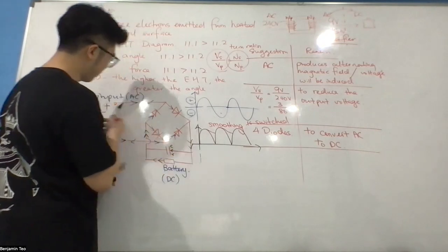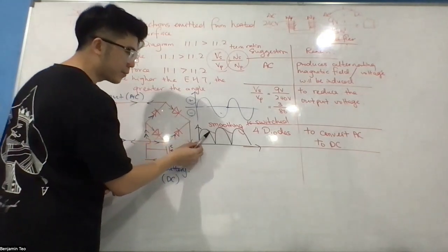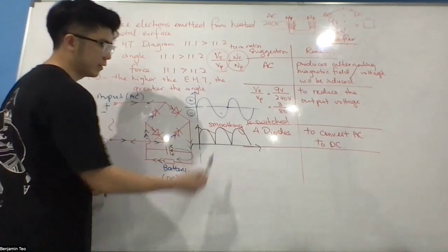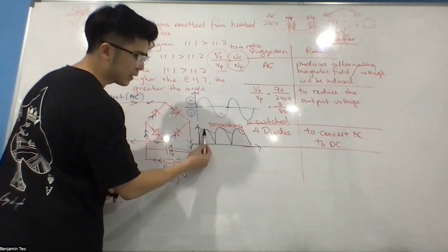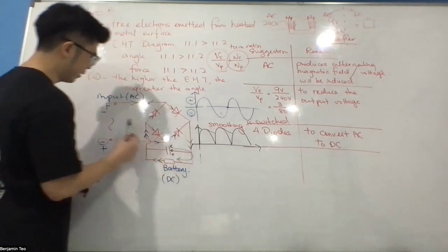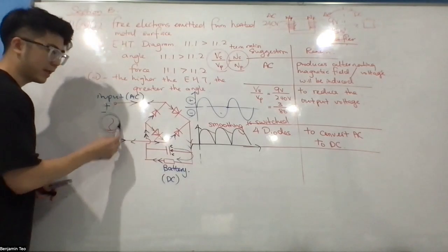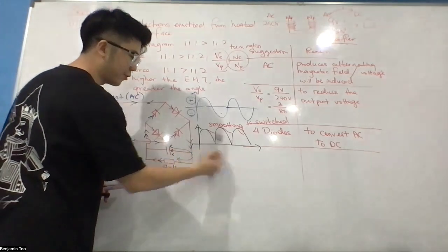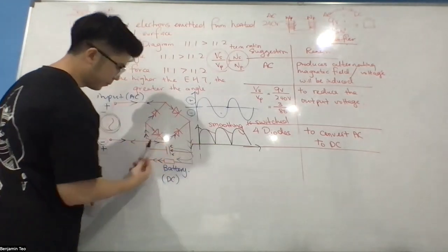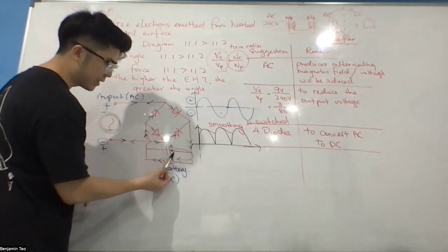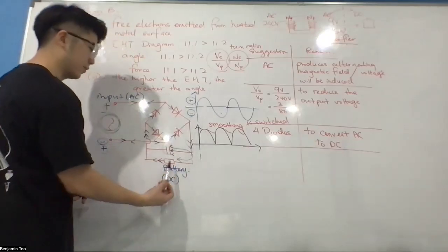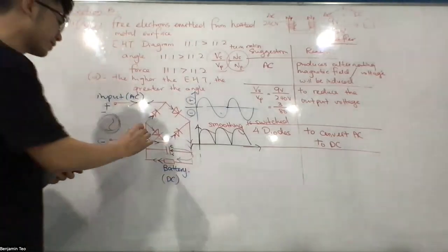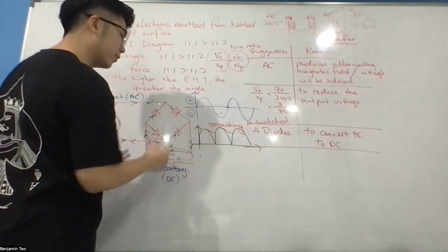So whenever the AC current drops, it will supply that charge. That's why there is no sudden drop here. Do not forget that your power supply is changing, it can rise and fall, rise and fall. When it is falling, this capacitor will release the charge to supply the battery. That's why this is not as steep. So the capacitor is to smooth out the current.